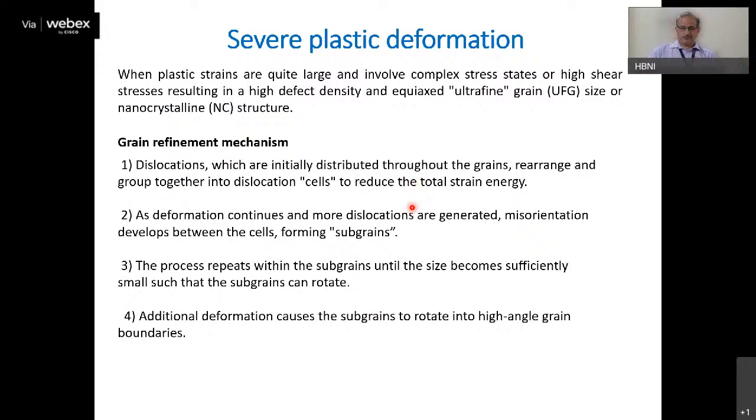So your material basically reaches some kind of saturated hardness state, and it becomes independent of the history or the pathway in which the plastic deformation has been applied. So this is the region of plastic deformation that is of interest for the study of plastic strain-induced phase transitions.